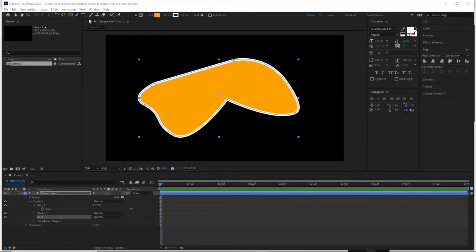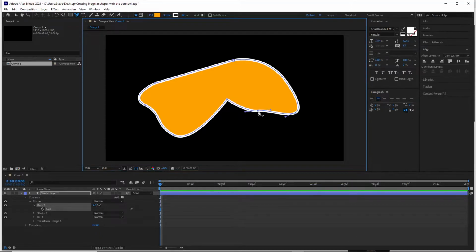The other thing that's just worth knowing about, so if we click and hold on the pen tool, you'll see this add vertex tool. If I select that, we can actually add anchor points after we've created the shape if we want to modify it still further. And again, holding down Alt, we can manipulate that anchor point. Okay. Again, if we hold down Control, we can select the move tool, and we can actually grab the anchor point and move the whole thing. Okay, so there's various things we can do there, or like I said before, just manipulate one side of the anchor point.